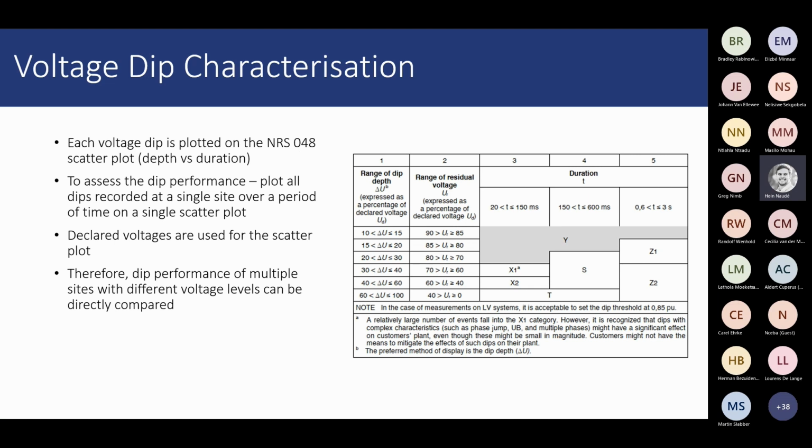Yeah, as you correctly mentioned, there's a few things that will impact the accuracy. But in terms of the Vector 3 specifically, that is a Class A device. We are obviously compliant to the highest degree of accuracy from the IEC. I just want to get that specific value for you. If I don't remember incorrectly, I think it's 0.2% or even 0.1% accurate on reading the value. So the device itself is extremely accurate, up to 0.2, 0.1% accuracy that you get.